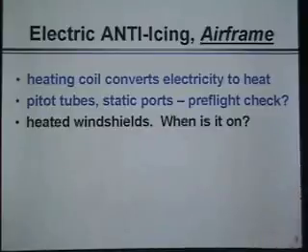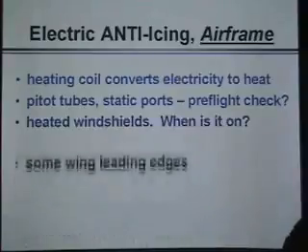Question? Are other windshields also heated except this glass? Well, there are other heated windshields, but the glass ones are the ones that you're worried about cracking, even if it's not icing. So if it's a glass windshield, you're going to turn the heat on just prior to takeoff, and you're going to leave the heat on until after you land.